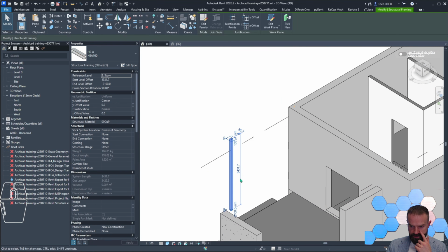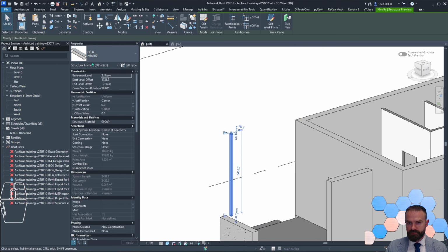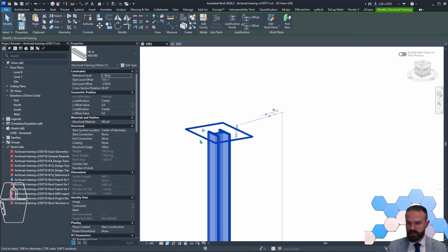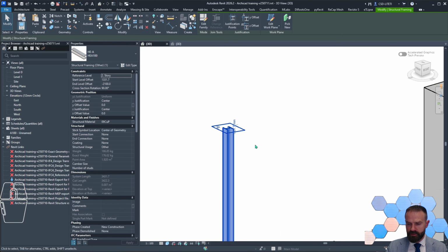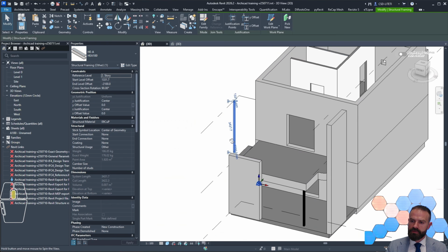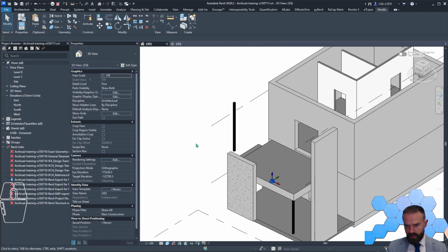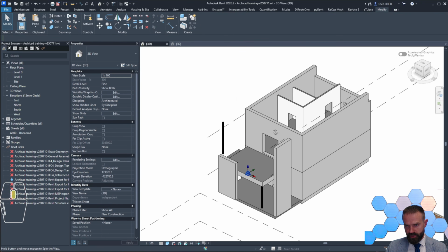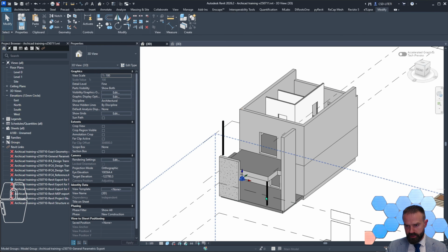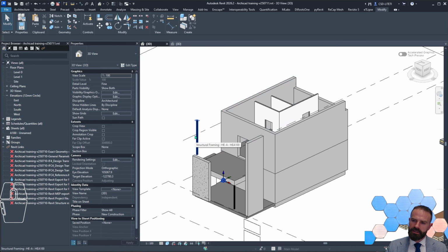And using Advance Steel, if you can see here, this column was transformed into structure framing object, and I can modify, and I don't have strange void object on the top of this one, but inside ArchiCAD it was a column. So looking from structural engineering point of view, it's not correct category in here, so maybe it can be modified in Advance Steel.